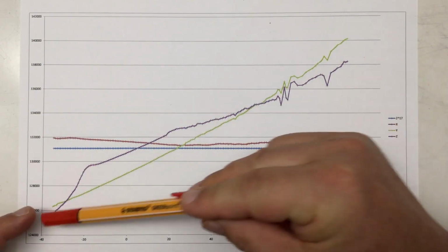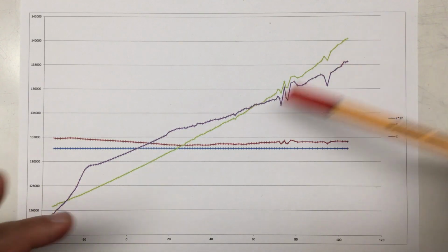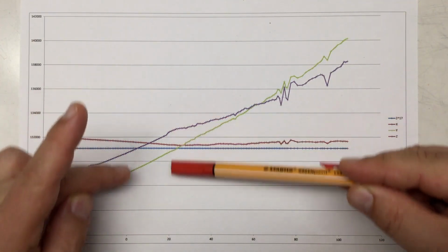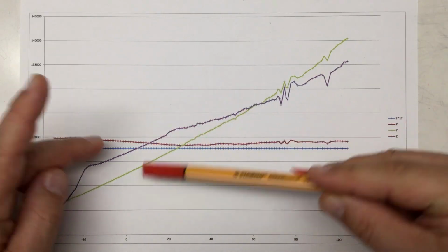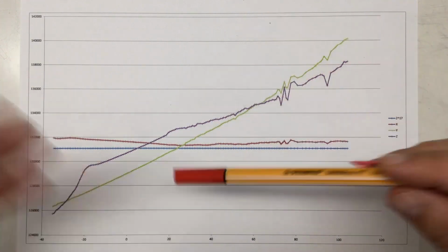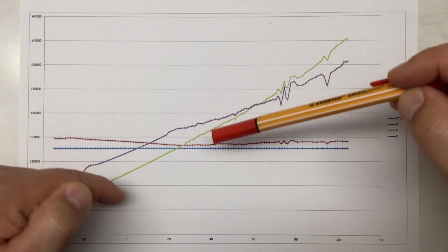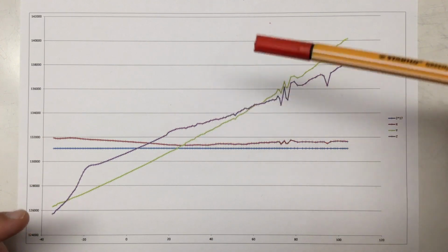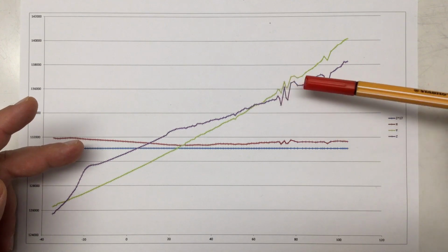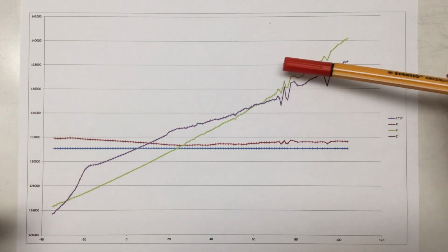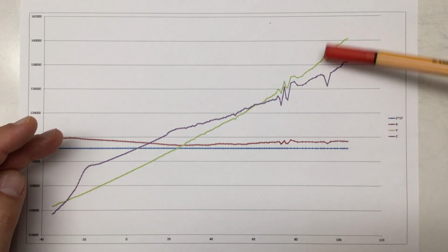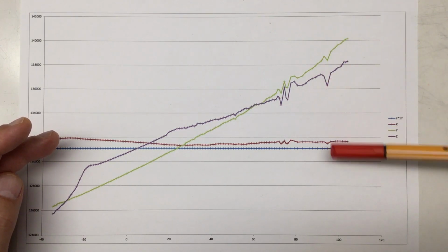Anyway, the changes over temperature, even if we look just at the area between 0 and 20 degrees, are enormous. And it's not really linear, so we cannot really extrapolate just between 2 points. You see there's a bump here. And in the higher temperature range, between about 70 and 80 degrees, we get these irregularities, which are repeated up here between 90 and 100 degrees.